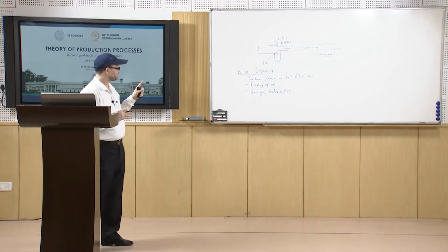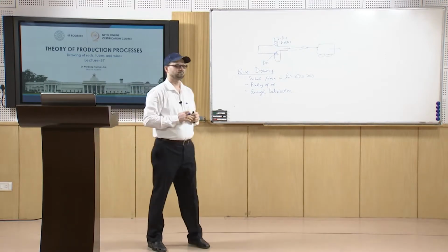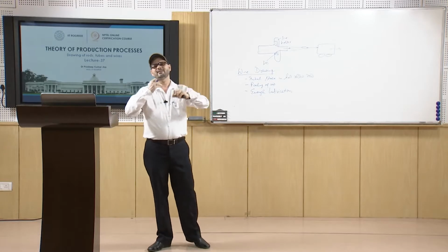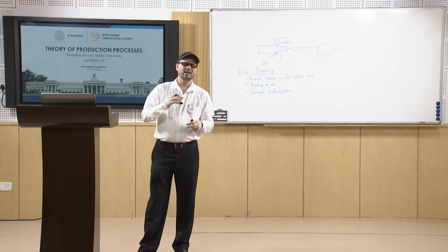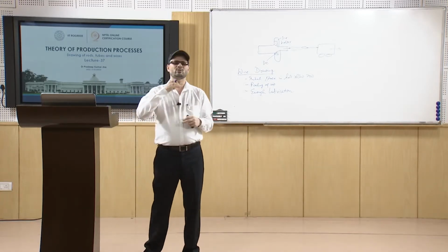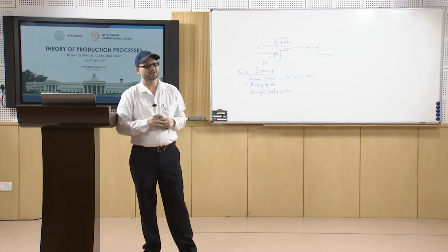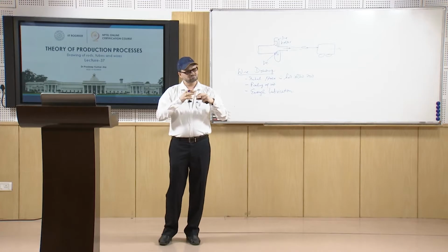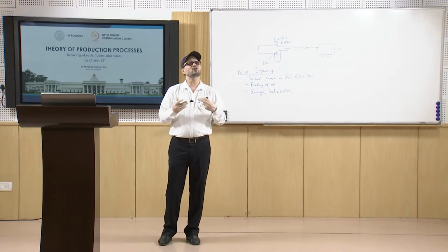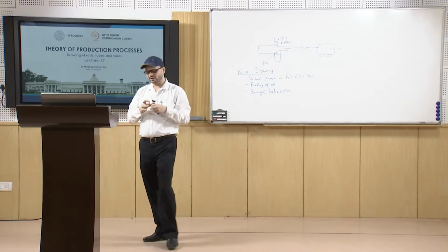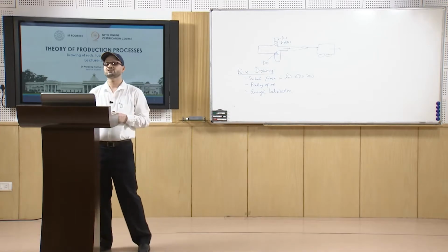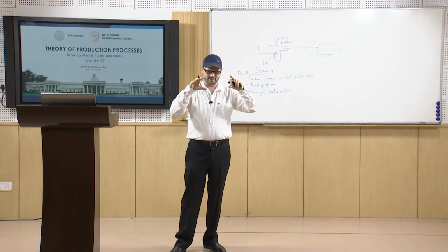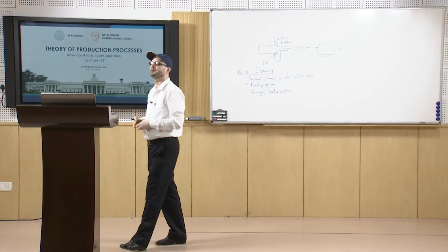Now, there is another kind of drawing, that is dry drawing, where you use a dry kind of lubricant or dry coating, and that works as lubricant. But many times we also adopt the wet drawing operation. In wet drawing, the whole unit is immersed in a lubricant medium.